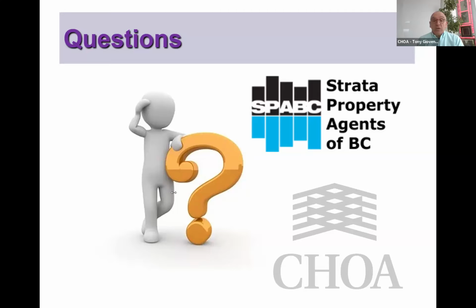Cheryl, your question is probably the most common that we're getting. We're only 12 units, built in 88, no plans to enable electric charging other than a couple folks who plug into existing outlets and pay $30 a month, which, by the way, a lot of buildings are doing, and it's working incredibly well without a massive increase on demand. If you have multiple charging systems, though, make sure that you're actually looking at a management system, because it really does help to distribute power more evenly across your use periods.